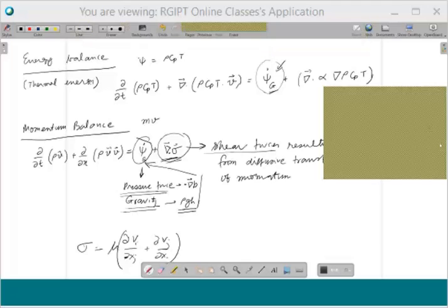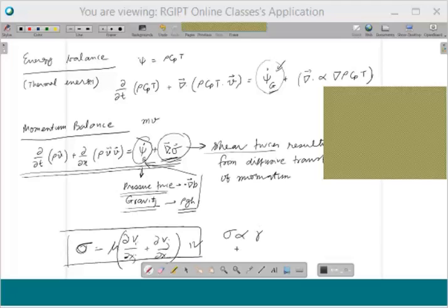Did you mean NS equation or NR equation? I assumed that you meant NS, Navier-Stokes. So this itself is not called Navier-Stokes. Remember, the Navier-Stokes equation applies to Newtonian fluids. So you have to assume how the liquid responds to applied stress in order to call it Navier-Stokes. When sigma is proportional to gamma dot, that is Newtonian fluids. And for Newtonian fluids, yeah, Rohan, I'm sorry, you have an 11:30 class.